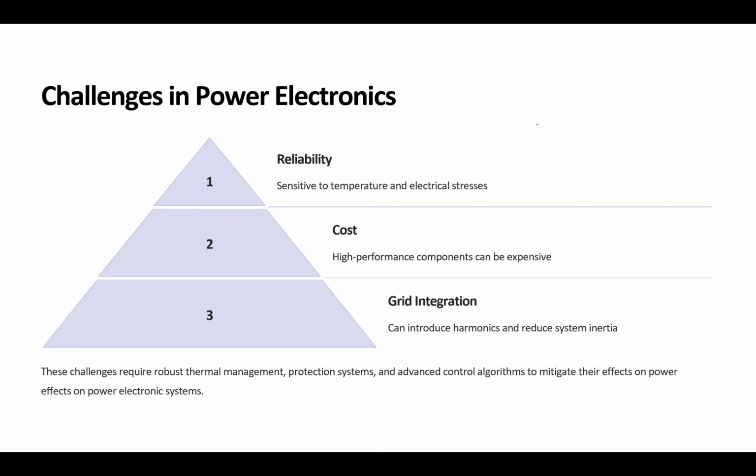Okay, now when we talk about the power grid, it's not just those frequencies. They are called harmonics. We have interharmonics. They could create interharmonics. We are going to talk about that. What are interharmonics? I'm just going to give you the keywords. Interharmonics are non-integer multiples of the fundamental frequency. So it's not like the converter could only create 60 and 120 and 180. No, there is 100 hertz too. There is 99 hertz too. Okay, the amplitudes are different, but it creates a lot of other frequencies and injects them into the system.